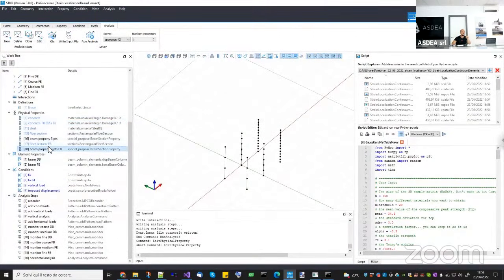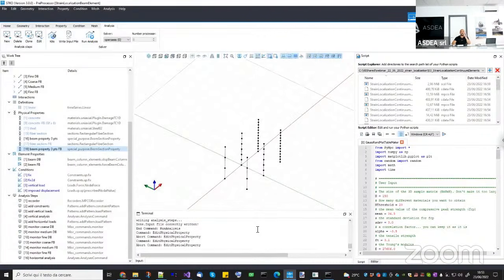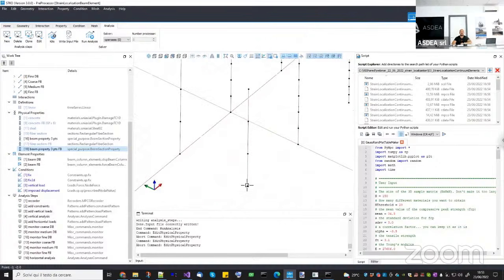Where are the 3 integration points here? The force-based element has 3 integration points, and it localizes only on 1 integration point. So it is not correct to assume that the characteristic length is the entire length of the element. Instead, for a force-based element, the characteristic length should be the length of the Gauss point.